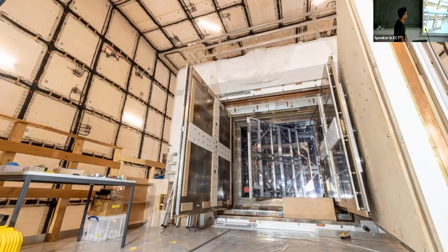That's just another image. And here, remarkably, you see this kind of grid. That's 55 kilometers of cables in 8 coils. And that's our new active compensating magnetic shield. So how it works is that we have, at a 1 centimeter distance around the magnetic shield, field sensors, and whenever they see a difference, we adapt all the currents in these coils accordingly so that the shield itself never sees a change of a magnetic field more than 1 microtesla. And so it stays very stable, and the inside field stays also very stable. So that's a measure of stability.